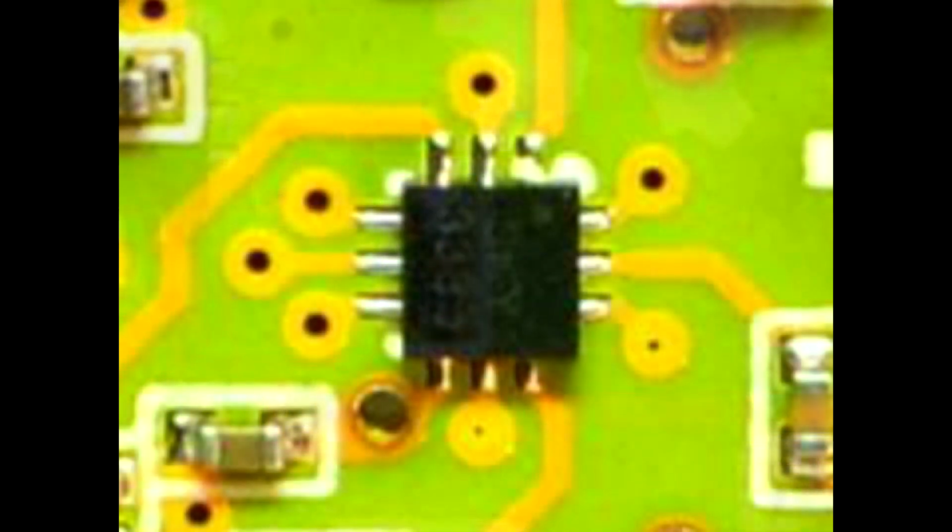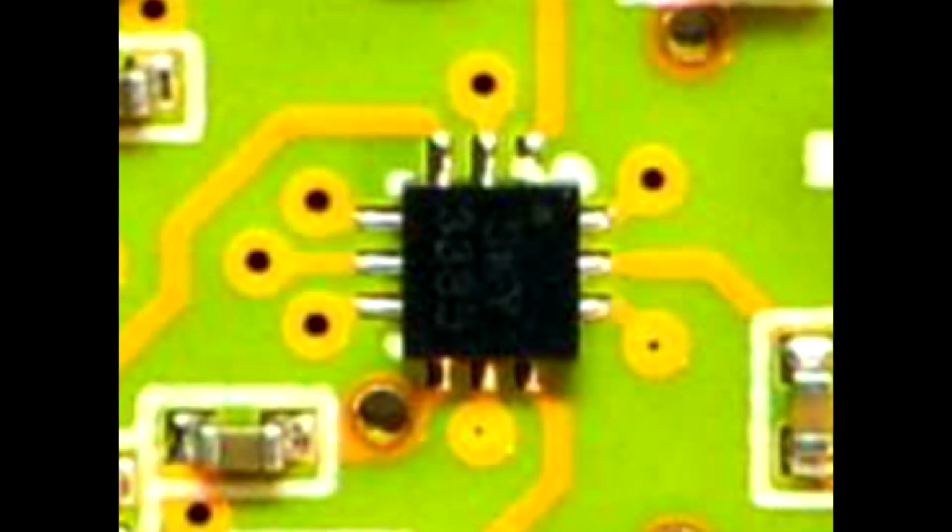So it goes through here, this is a capacitor, and notice it just goes through it in series. That's called a DC blocking capacitor. We'll talk about that a little bit. But RF goes right through it, and it hits this part, which is an RF switch. And now there are three paths to get from this switch to that switch.